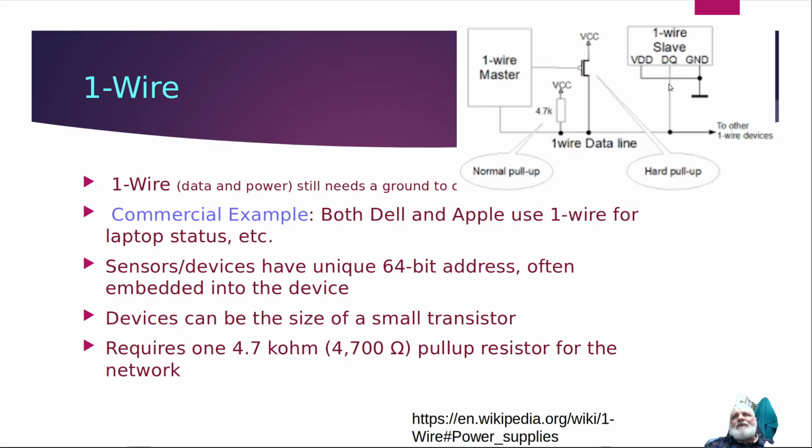Now, one thing I will say, I've noticed when you buy some of these temperature sensors and things that are using one wire, some of them do not support the actual one wire. They actually still need their own separate power. So technically they're not supposed to. They're supposed to be able to be wired as I show in the slide here, but if it doesn't work, try providing it its own voltage source on the plus pin. This is the plus pin VDD here.